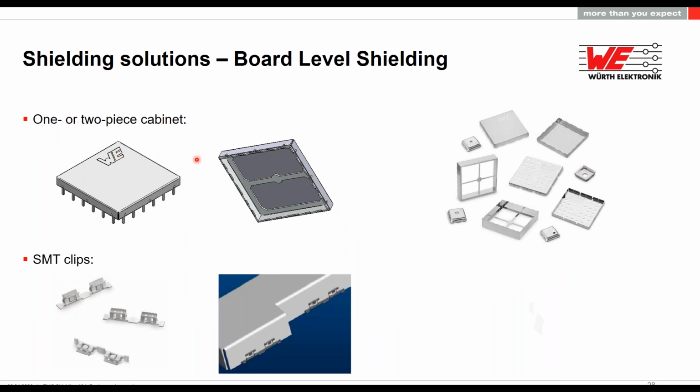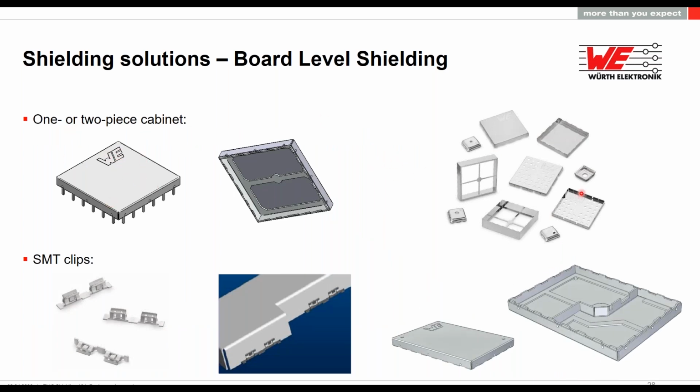They normally come either in a one-piece solution or two-piece solution, depending on if optical inspection is necessary or not after soldering. Also, they can be used with SMT clips, but only the one-piece solution, in order to make them pluggable. They can normally be customized with different shapes and internal compartments in order to separate different stages of our device. This is really common, for example, in mobile phones, computer boards, and so on.